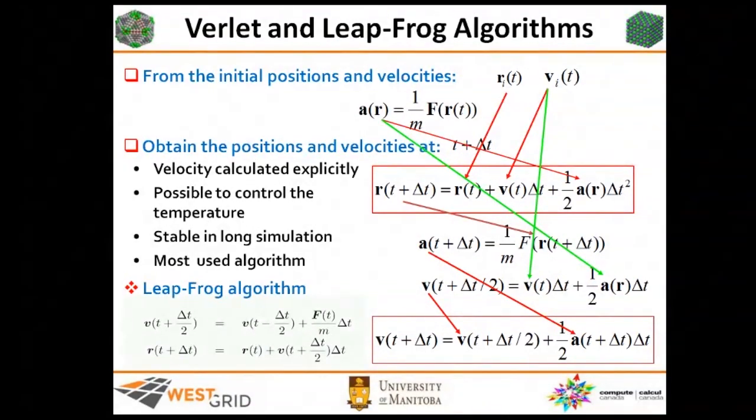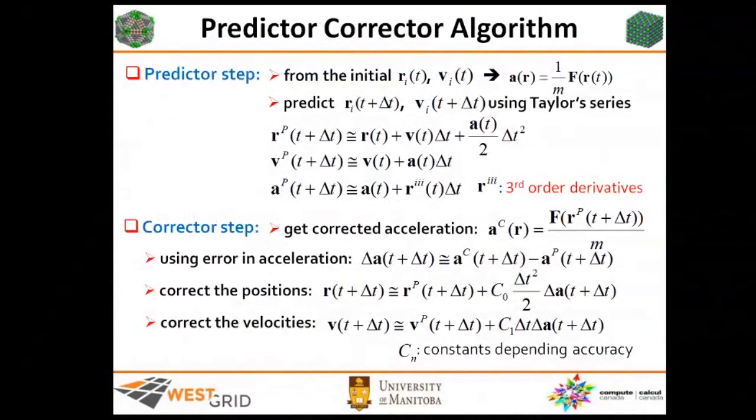Now, how to set up an MD simulation? For any MD simulation, you need to set a few things before starting to run. For example, you need atomic positions. Even if you are using quantum calculation, you always have to set some configuration, so the positions of atoms. You also have to set the density. Your density should be the real density.